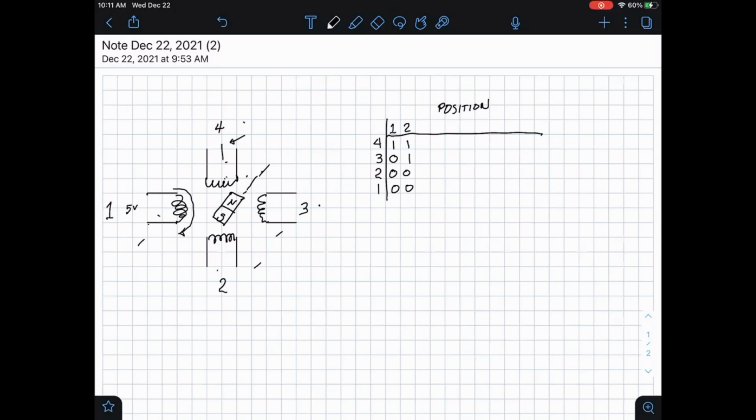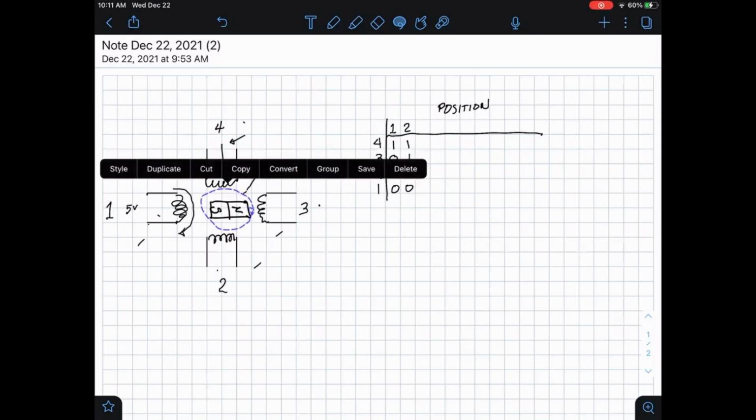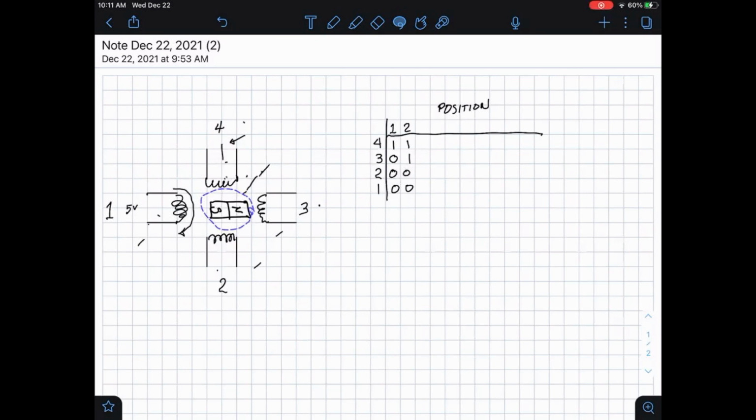So you can imagine that is how to control the shaft. Just turn on and off the magnets in sequence. So if we now want this coil to further move this way, rotate this way, anong gagawin natin? We turn off everything except coil 3. We turn on the magnet of coil 3, okay, and turn off everything else. And now it's in the third position.